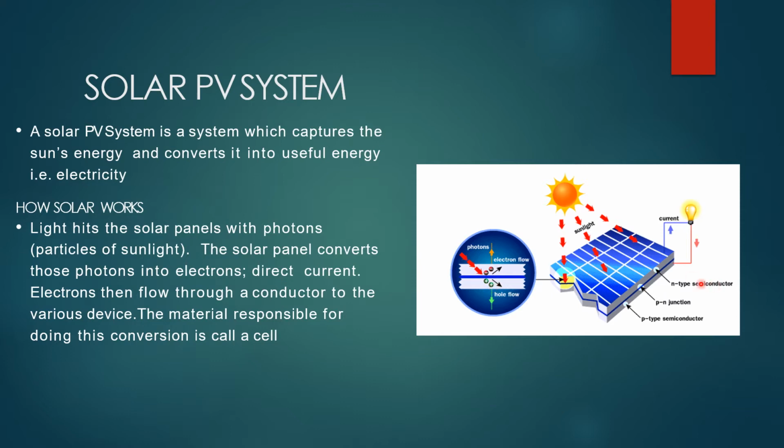When sunlight strikes the solar cell surface, the cell creates charge carriers as electrons and holes. The internal field produced by the junction separates some of the positive charges from the negative charges, and the holes are swept into the positive or p layer and electrons are swept into the negative or n layer. When a circuit is made, free electrons have to pass through the load to recombine with the positive holes. Thereby current can be produced from the cells under illumination.